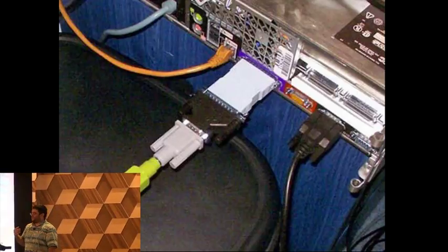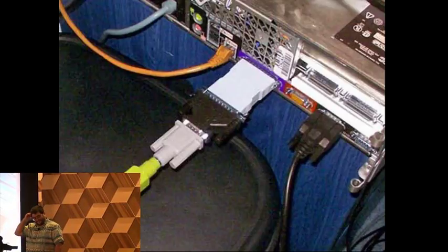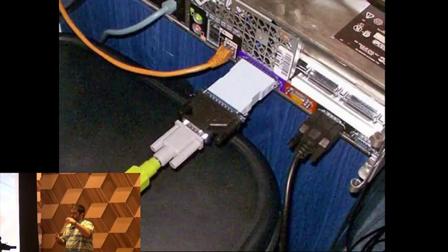Well, first off, nothing ever is simple in the embedded world. At least mostly never simple, because you have to find the Flash program, because every board flashes its memory differently. I mean, you could have 12 different ARM boards, all running the same CPU even, and they use 12 or 13 different ways to actually flash all of the boards.